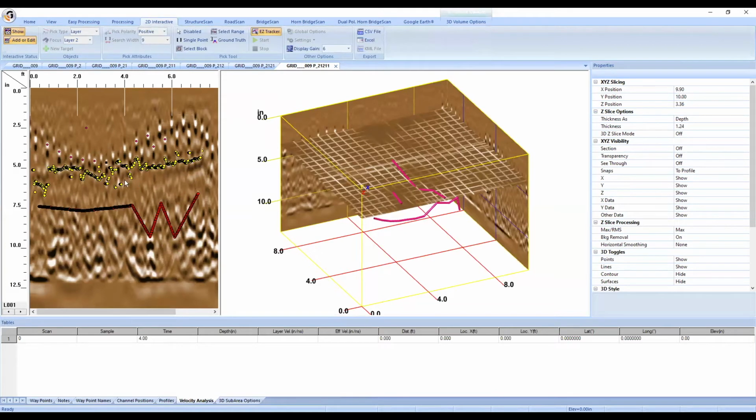So my second question is, let's say the field crew went to site and they forgot to calibrate the dielectric or they used the wrong dielectric. And we end up getting a different depth coding from the GPR. Is there an easy, like one click, fixing? Because I have the core depth and I have the scanning depth, which are different. Other than the dielectric you showed earlier, is there any other way I can do it?